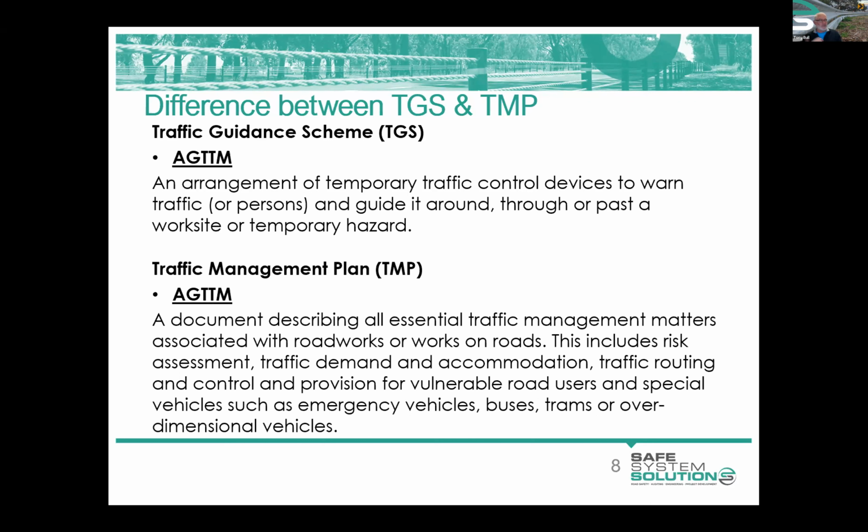This includes a risk assessment, traffic demands and accommodation, traffic routing, control and provision for vulnerable road users, and special vehicles, such as how we're going to manage emergency vehicles if they need to get through our sites. Looking at bus timetables, tram movements, even over-dimensional vehicles that might be on an over-dimensional route. It's all those items that you need to consider. So that becomes your plan.